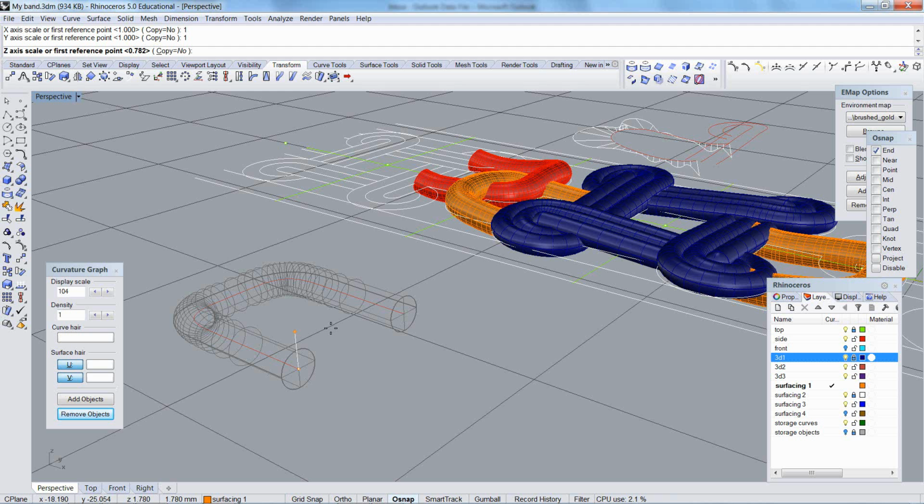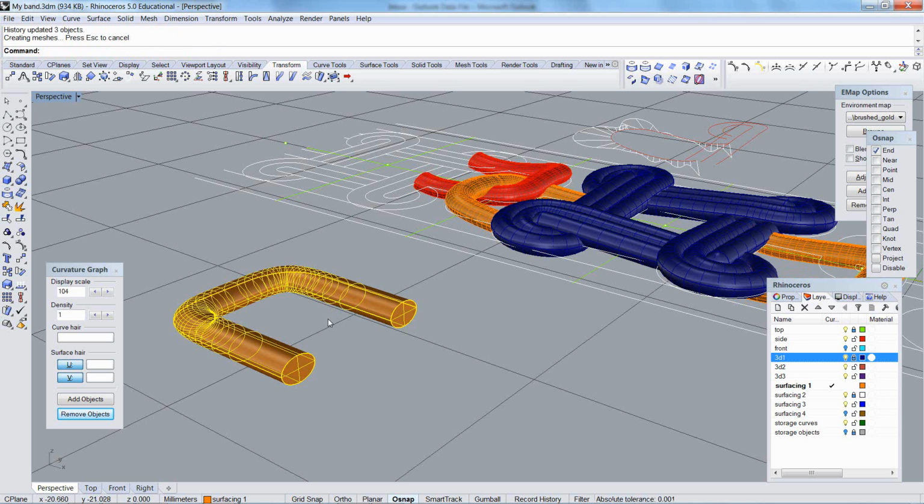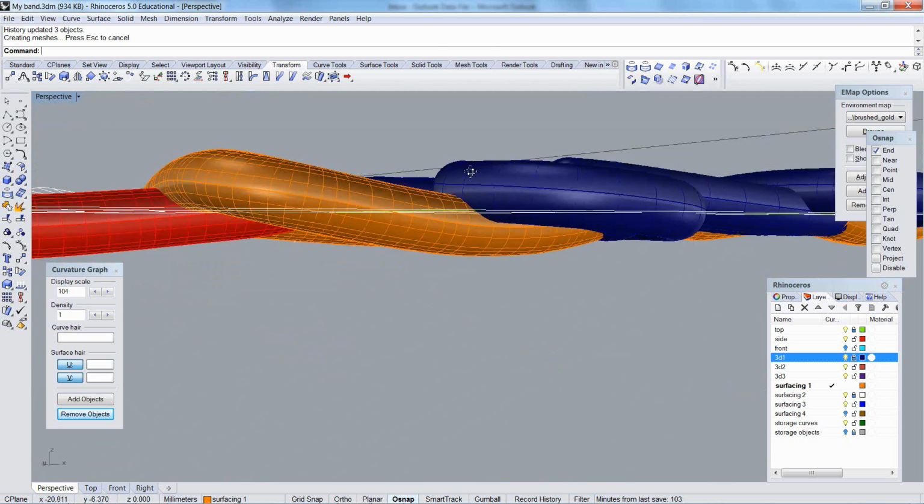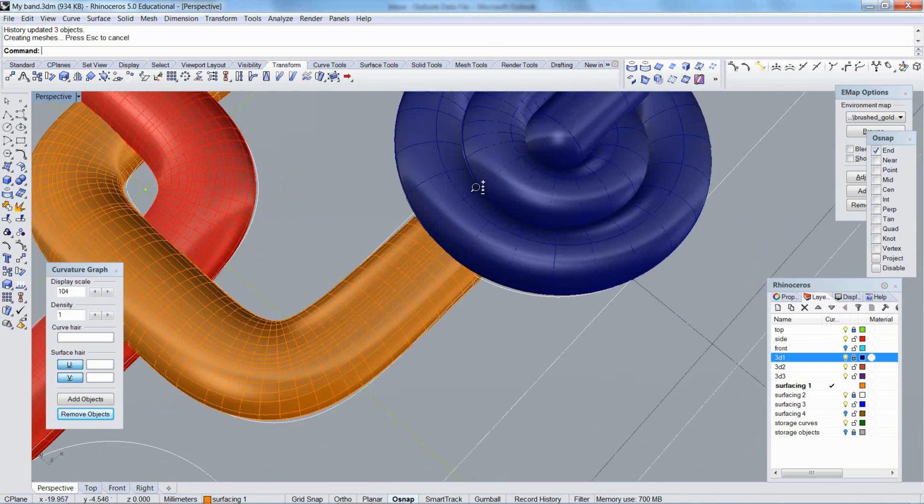Rhino has a wonderful feature. You can actually, to get a number, I hope it works, sometimes it doesn't. If it doesn't work, I'll have to get a calculator out. But usually Rhino lets you run a calculator in the context of your command. I want this to go from 1.8 to 1.3. Those other pipes are 1.3. So I can type in 1.3 / 1.8. 1.3 divided by 1.8, and Rhino will do the math for me. And this is now exactly 1.3, which means this is now exactly the thickness of my other pipes.